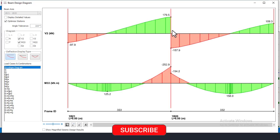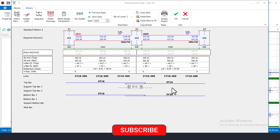Okay, so you can see that for this moment now, what the maximum here is showing is minus 252.9. That's why we are having that support reinforcement there at the top to be able to take care of this moment here. Okay, so I'll just click on here and then click on here, exit here. And then we can arrange this bar like this by having 4Y16 at the first top layer and layer 2 to be 3Y16 only at this support here.